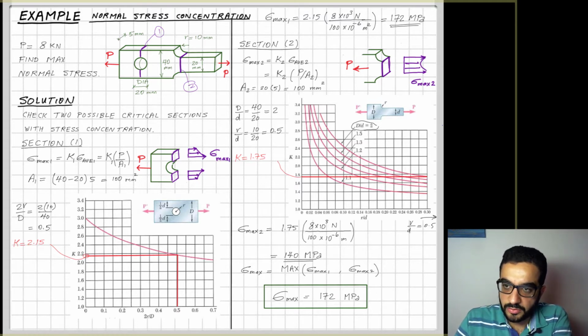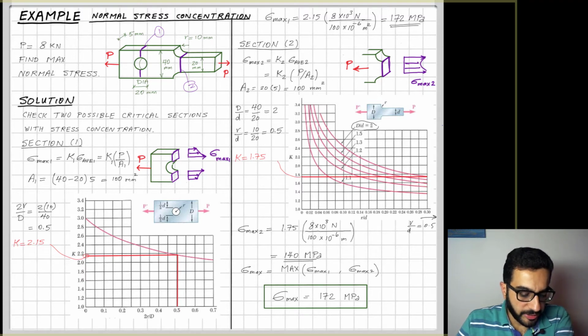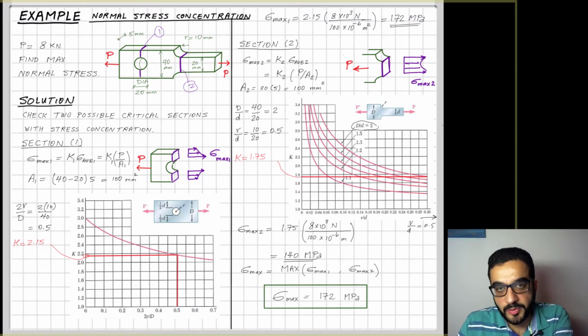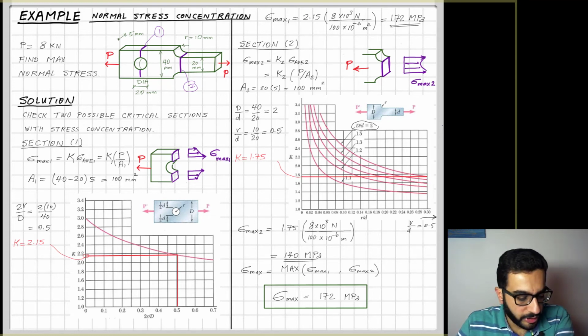So that was a quick example here of how this stress concentration concept is adding that little step to acknowledge that stresses kind of concentrate around the transition of my cross sections or the points where I do machining to the material. So pay attention to that, and it's really critical because materials fail at small points in a member and a structure, and that kind of causes failure over time. So little things, little failures can cause big failures at the end.